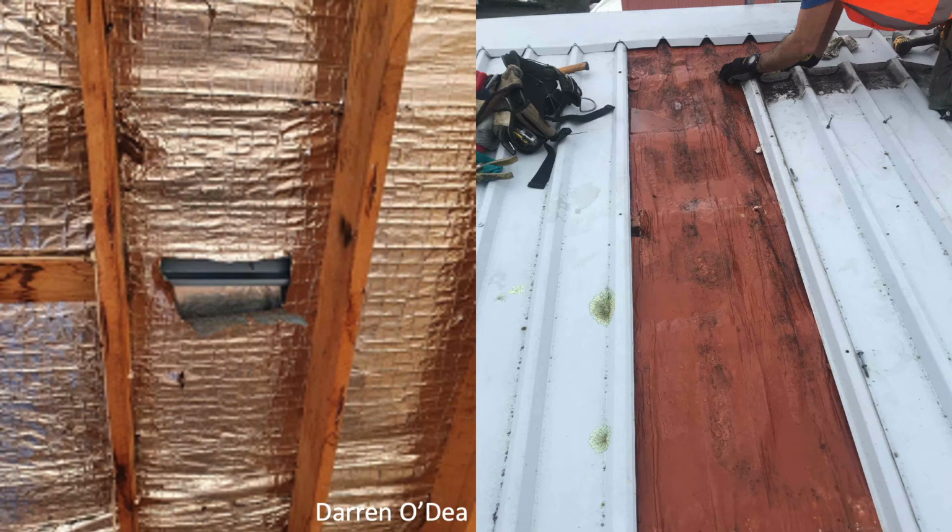And what often happens is that the occupants of that building call in someone to find the leak in the roof, and often there is no leak in the roof. The rain is essentially being generated from the warm, moist air inside the building, finding its way up to that cold surface and condensing, and that's where the water's coming from.